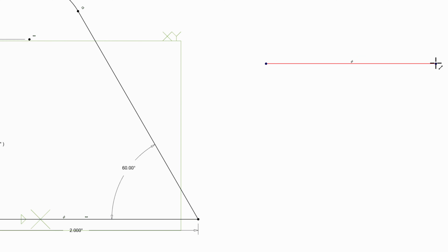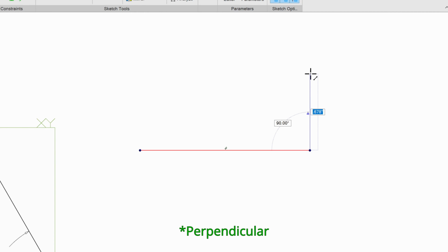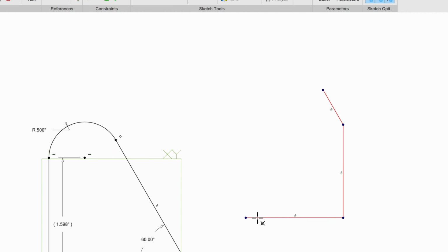And if I click, then that's automatically applied, right? Likewise, if I go straight up, I get that blue little vertical symbol that shows up, and so on. So if I do this at just the right angle, you can see that I get another parallel with that angled line in my sketch. So automatic relations can be applied when sketching to save you a lot of time. And so when you're sketching, be aware that automatic relations can show up and be applied.